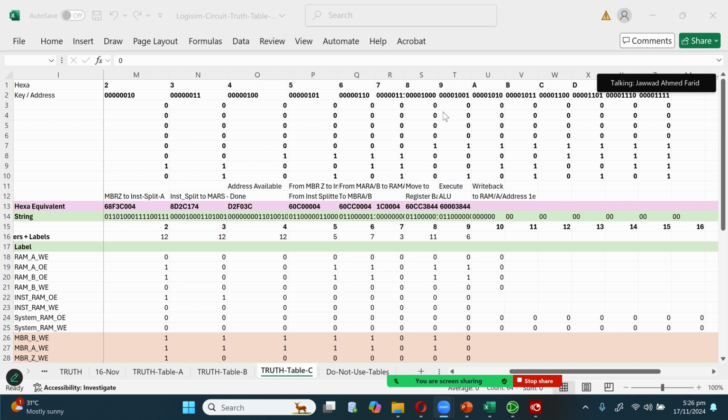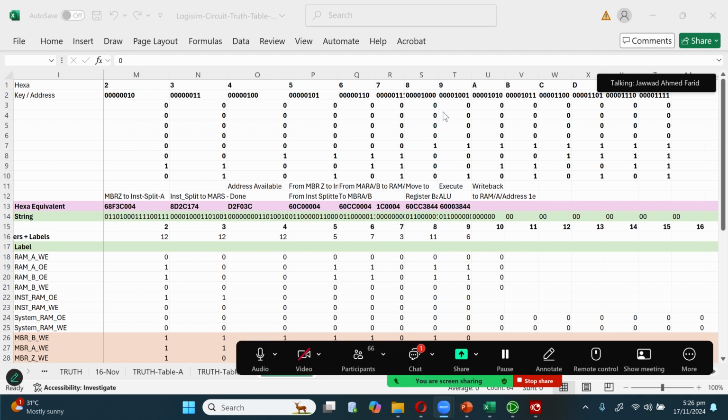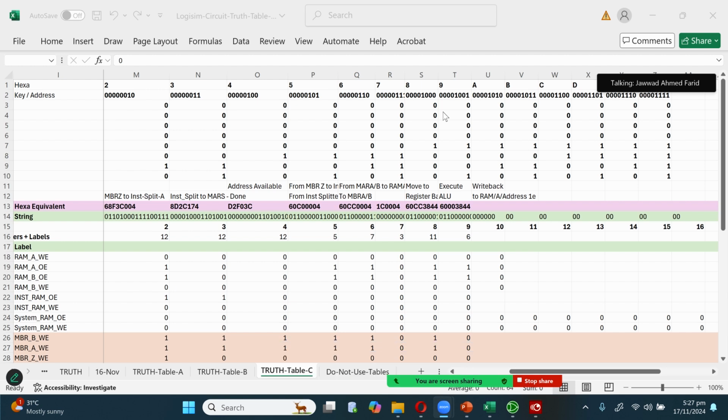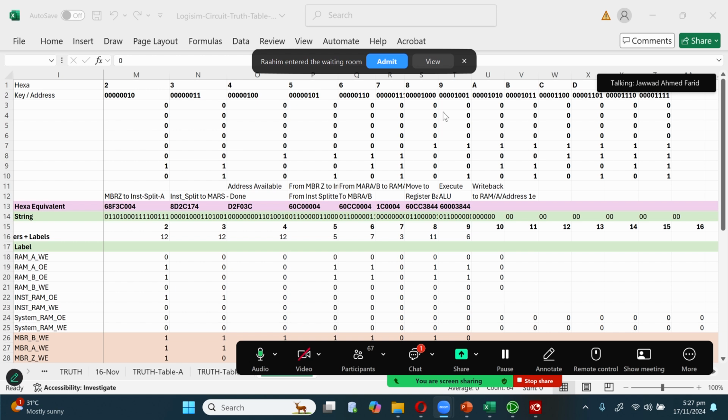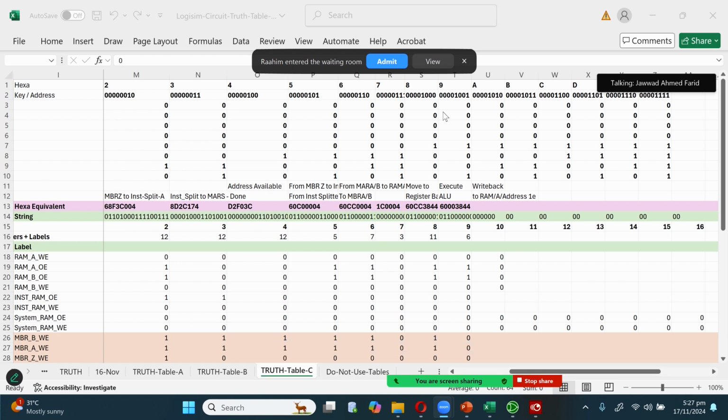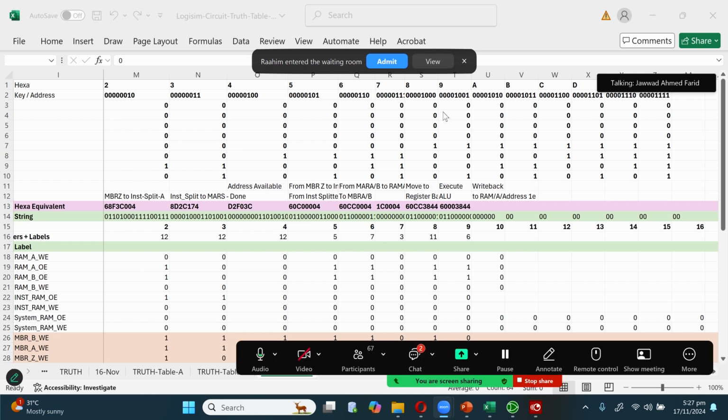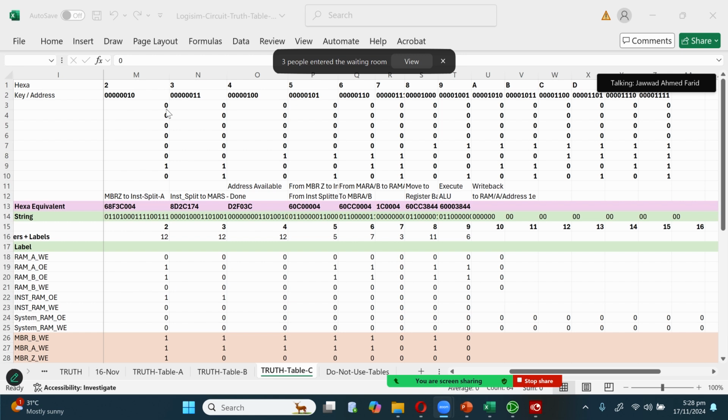मेरे पास इस वक्त मसला ये है कि जो मेरा सर्किट, जो मैंने रोम का सर्किट इस्तेमाल किया है, उसमें जो मेरे पास एड्रेस बस है वो 8 बिट की है. And my guess is I can use 5 bit का opcode and 3 bit, but that means that I need to execute each cycle or each instruction in about 8 sub instructions. So if I can do it in 8 sub instructions, I can use the 5 bit का opcode and I can use the 3 bit का clock cycle. So ये जो दोनों का combination है, opcode and clock, this is what would essentially become your micro program for the program controller.